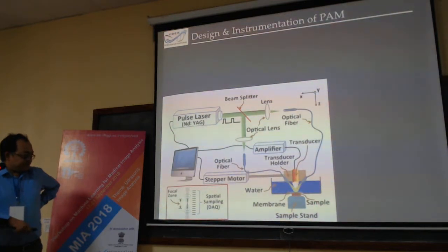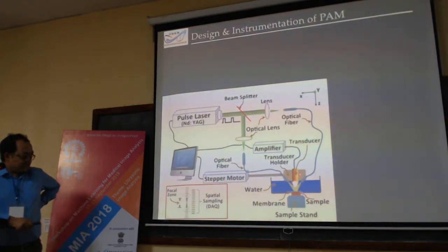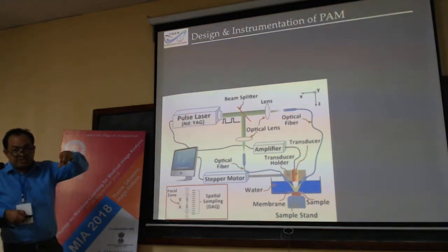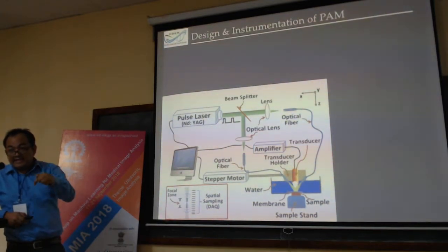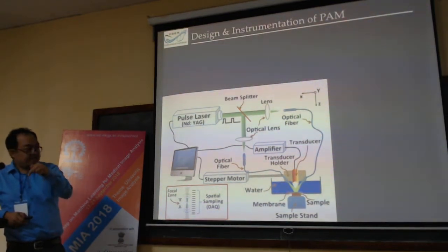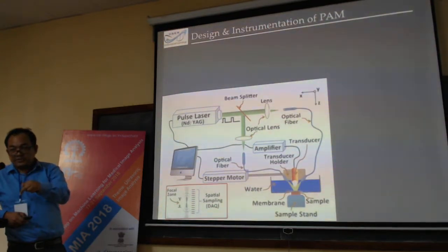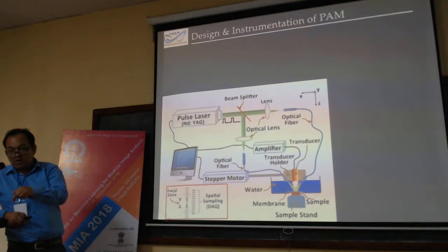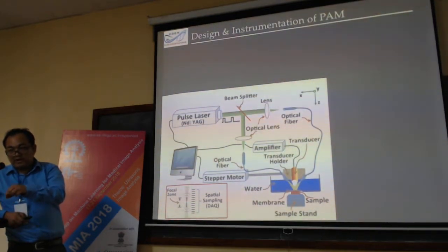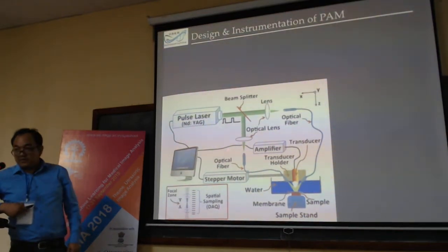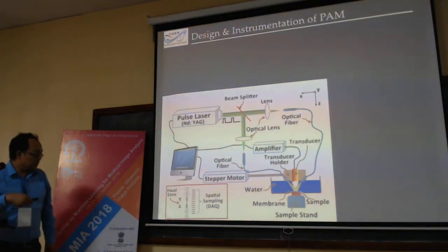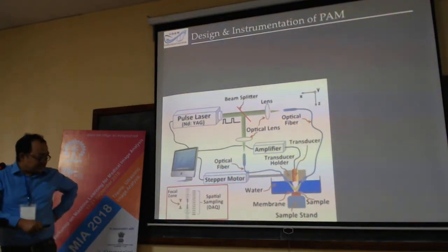So in this way, the photoacoustic signal is detected and collected at a given transducer position from the tightly focused region, such that A-scan data is achieved by collecting and transferring the photoacoustic signal over very narrow regions, using a data acquisition system with very high sampling rates. We use around, say, 200 megahertz. So at one scanning position we get